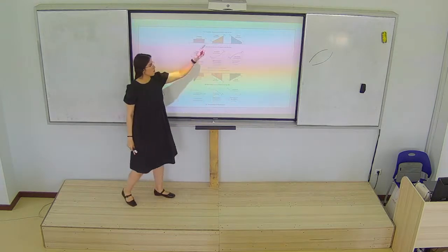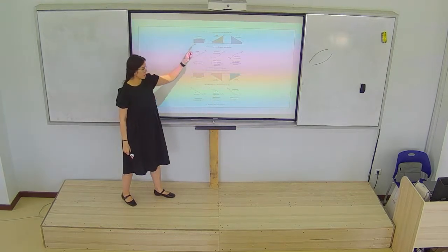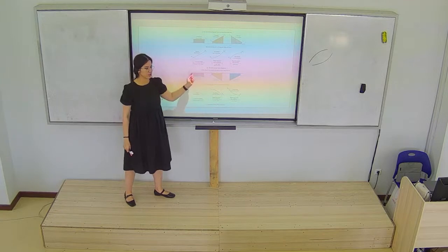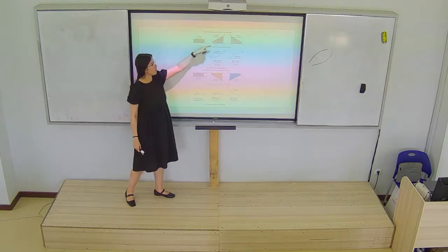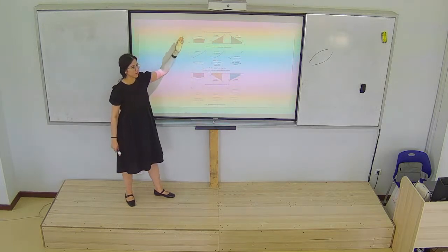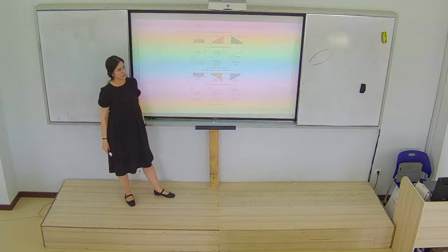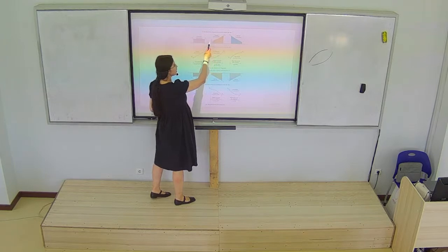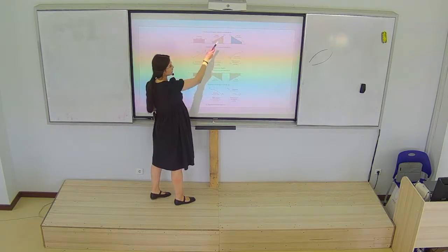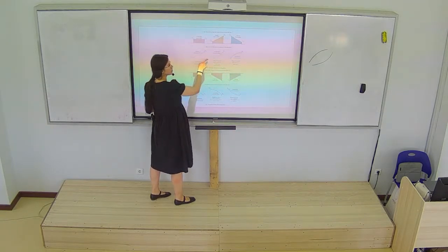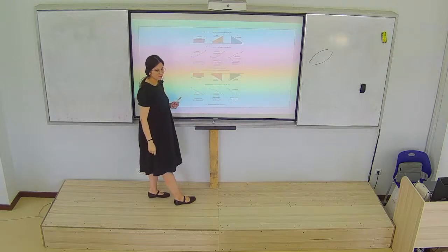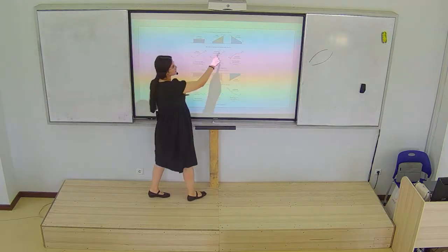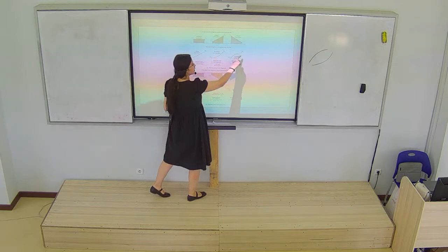This one is for positive shear. This one is for negative shear. As I told you, if we have a line, the upper part is positive, the lower part is negative. If the shear force diagram is increasing on the positive side, the moment diagram slope will be drawn like that. If it is decreasing, our slope will be like that.